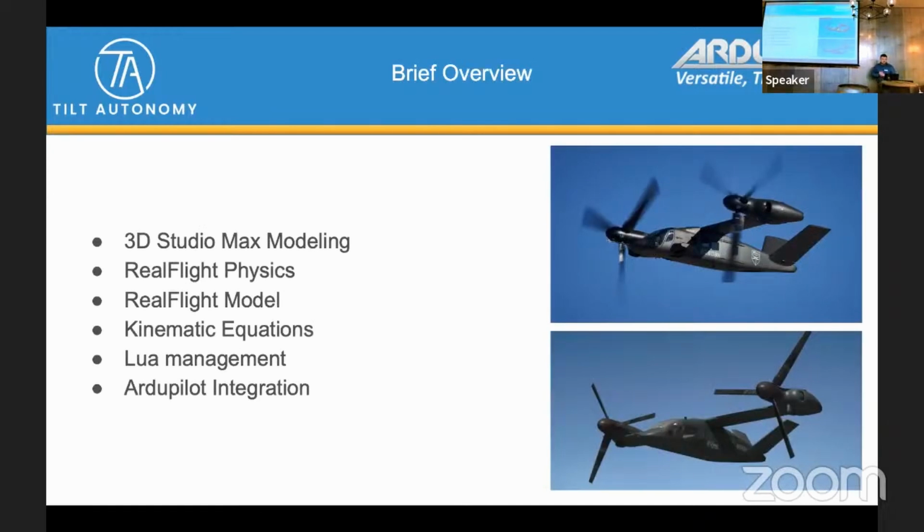So, brief overview of what I tried to accomplish. The goal was to create a high fidelity tilt rotor model specifically for ArduPilot SITL. The steps that I took were 3D Studio Max modeling, and then of course inputting the RealFlight physics, and then testing out the model in SITL itself, kind of evaluating some kinematic equations to make them better, and then what is required from a Lua management perspective, and then sort of what's needed going forward from an ArduPilot integration perspective.